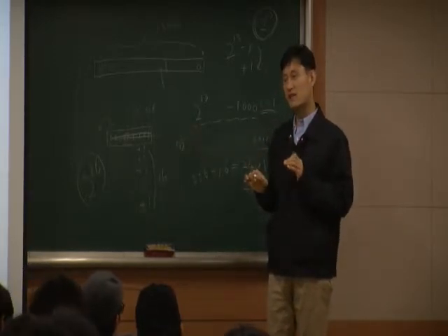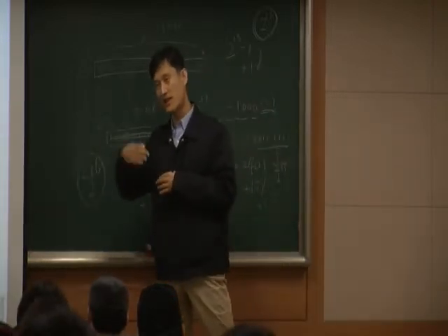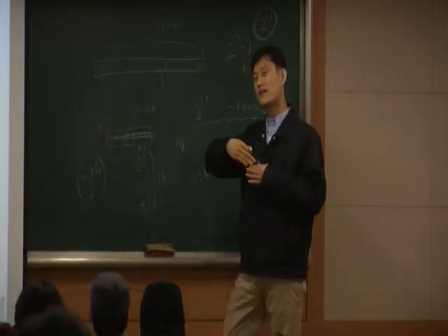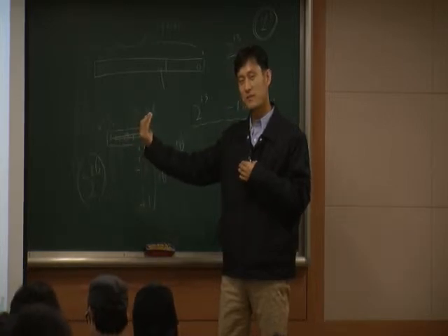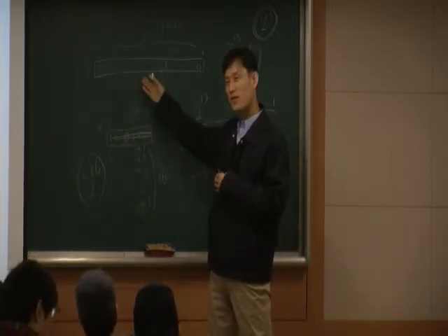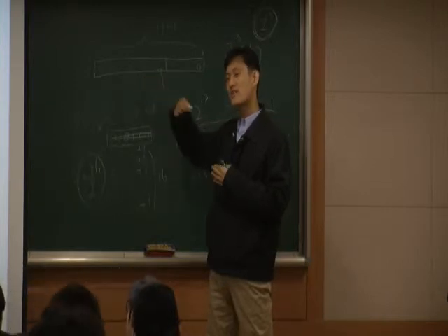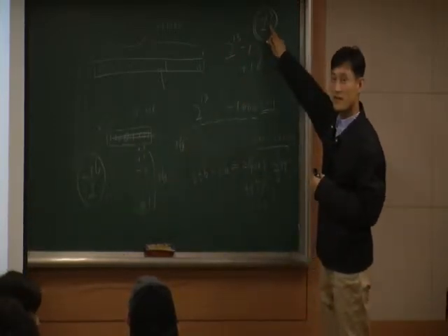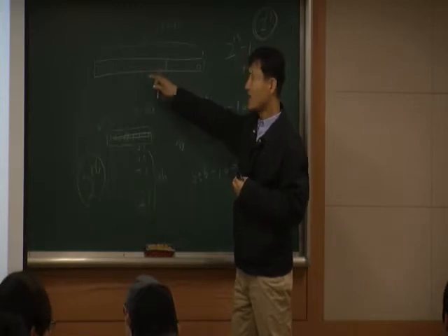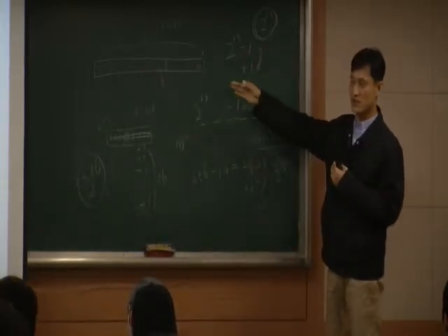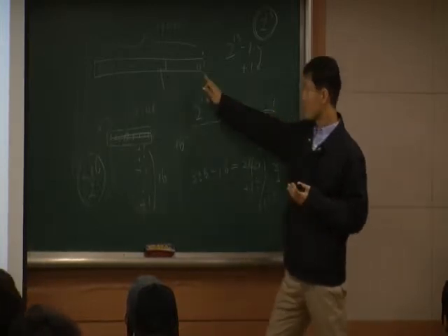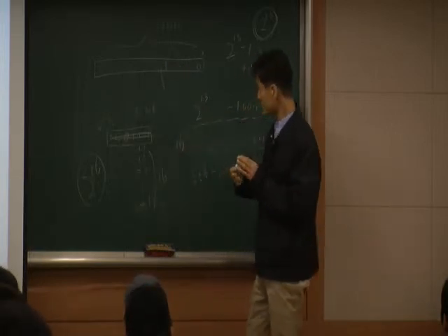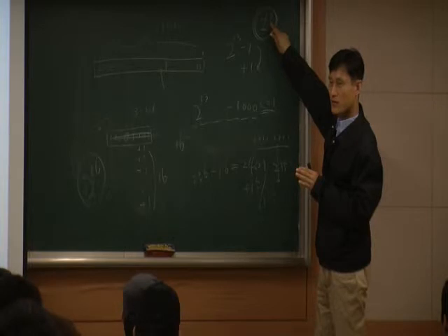But that's not the end. We want to measure another millisecond from that time. Okay, we want to keep measuring milliseconds. So from here, we want to delay another millisecond. Now what's the problem? This value now becomes 0. Okay? So when is the time that we have another carry on? This time, right? Because at the very beginning, we write this value as the initial value. But once the carry is on, the value remaining in this register becomes all 0. So from that time, it takes this much time to become another carry.